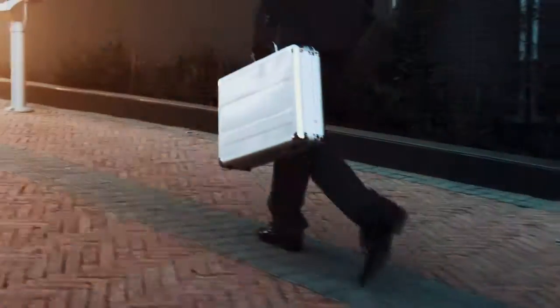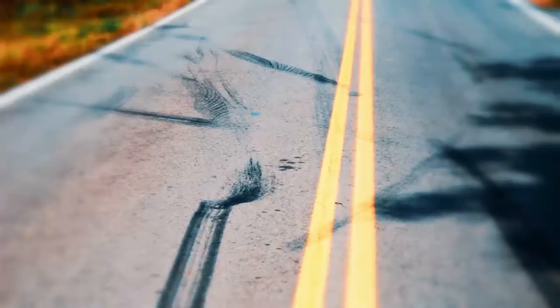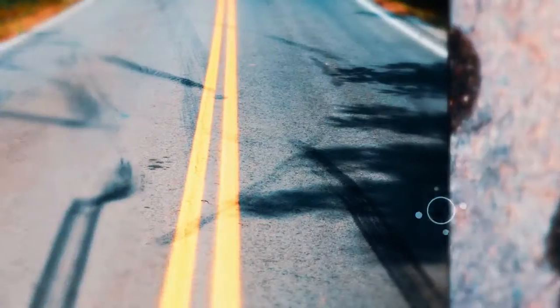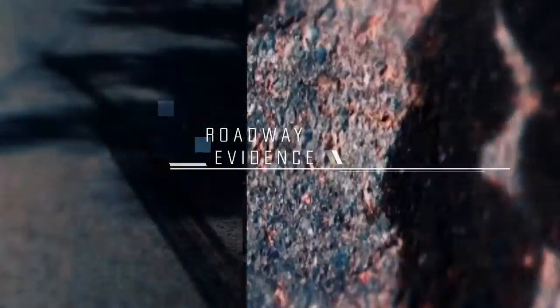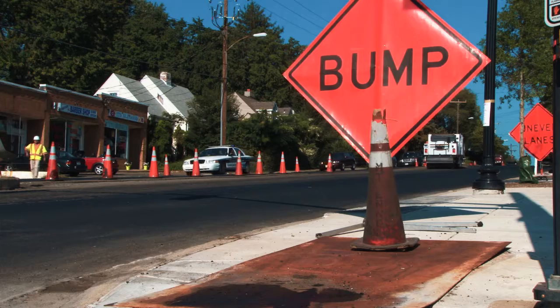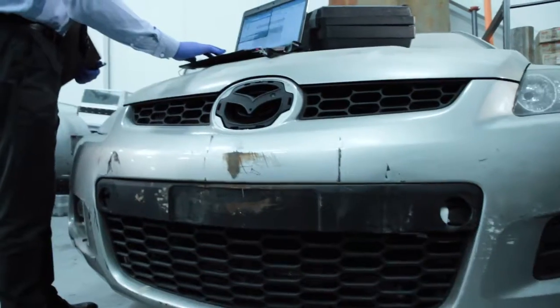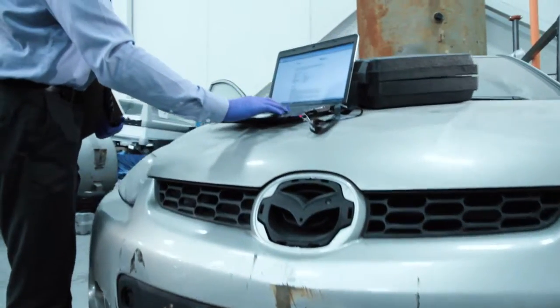The inspection of the collision site involves surveying the roadway and documenting through photographs and survey roadway evidence such as gouges, tire marks, fluid stains, final rest positions, debris. And also with regard to looking at, are there any sightline issues, or are there any roadway issues that may be a factor in why this collision occurred.